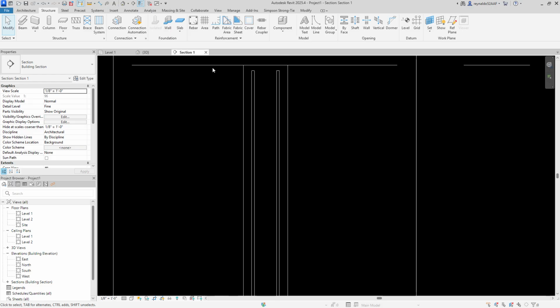To do that, again, you would go to your covers. You would click on one of the edges, and then you would change this to 1.5 inches, which is already set at 1.5 inches. We'll click on the outside one, and we'll make that 1 inch. There we go. So one's 1 inch, other one's 1.5 inches.